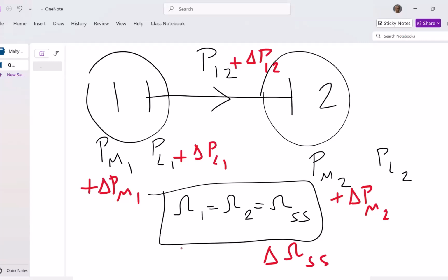All right. Now, there is a change in the load in area number 1, and that could happen in any area. So for example, 10 megawatts was changed in area number 1. Based on the contract that existed between the two areas, we were supposed to transfer 100 megawatts from area 1 to area 2. Now, because of that 10 megawatt change in load that happened in area 1, instead of the 100 megawatts that we were supposed to transfer from area 1 to area 2, now we're transferring 95 megawatts, for example. Is that acceptable from a power market standpoint?